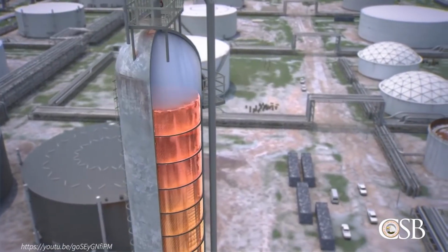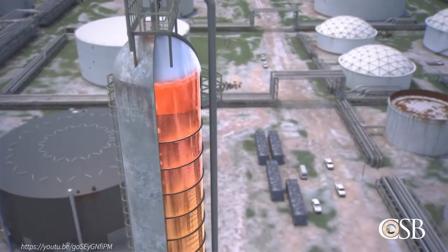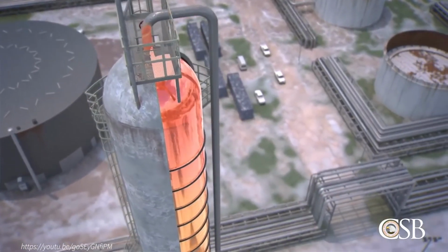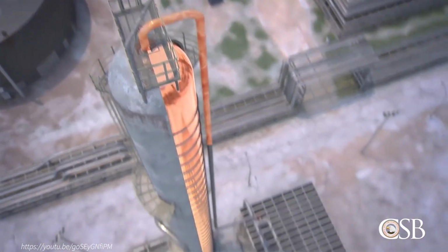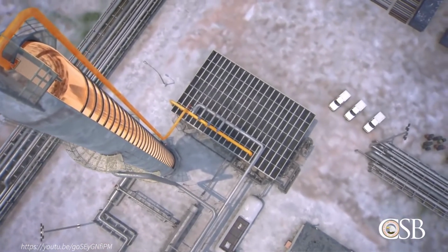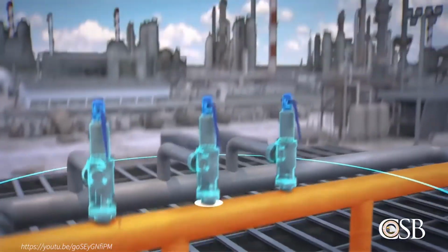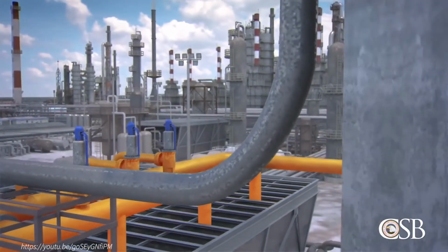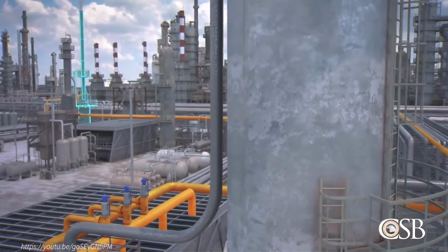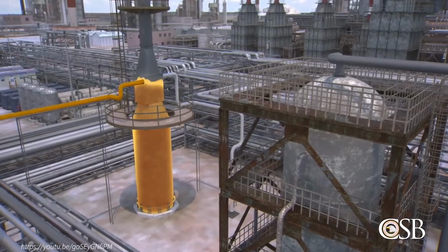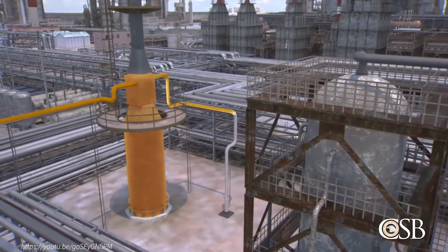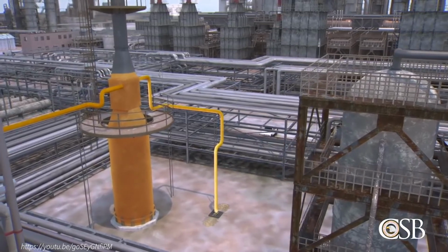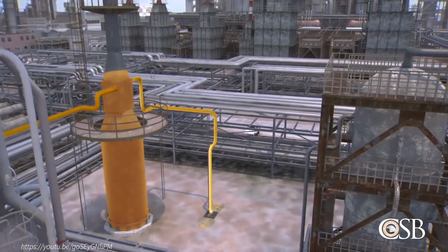The hot feed entering the tower caused the liquid inside to start to boil and swell. Liquid filled the tower completely and began spilling into the overhead vapor line, exerting great pressure on the emergency relief valves 150 feet below. At 1:14 p.m., the three emergency valves opened, sending nearly 52,000 gallons of flammable liquid to the blowdown drum at the other end of the ISOM unit. Liquid rose inside the blowdown drum and overflowed into a process sewer, setting off alarms in the control room. But the high-level alarm on the blowdown drum failed to go off.